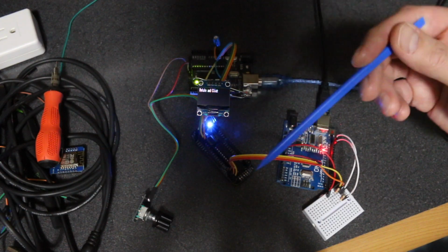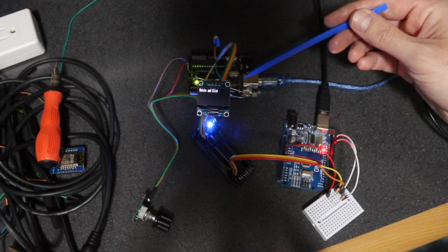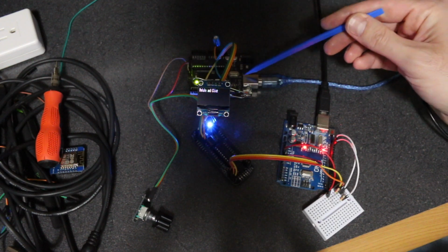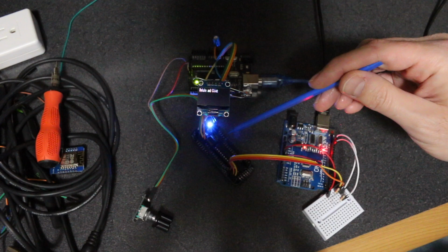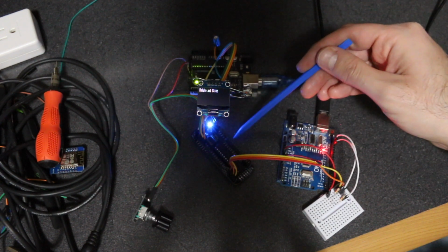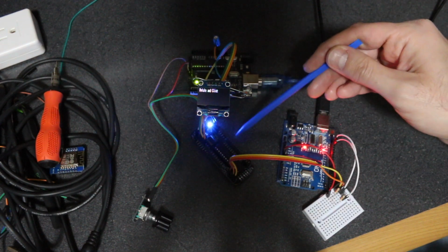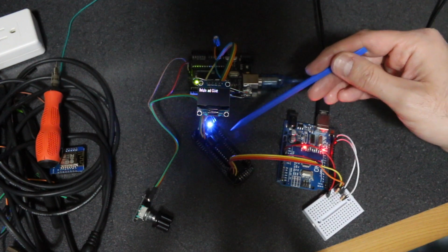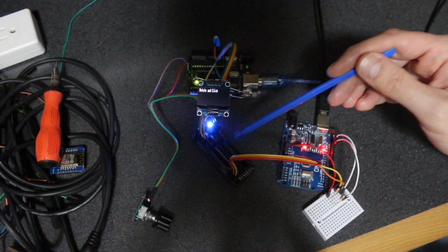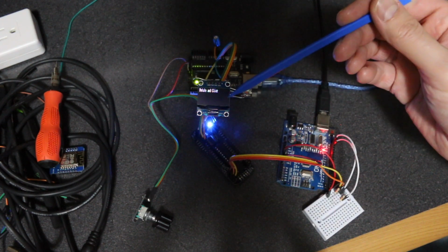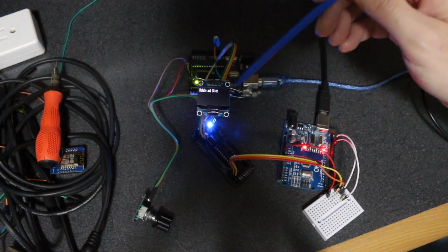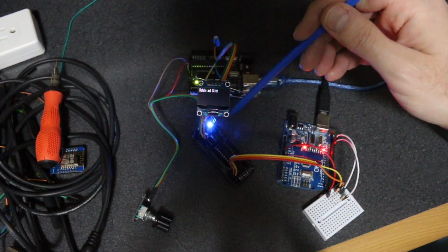This is the test setup, and here is the JTAG UPDI programmer for the ATtiny 1604 on this board, which is just some older design. I'm just using it because it has that chip and it has I²C pins. Then I've connected the OLED to pins that will have software I²C.